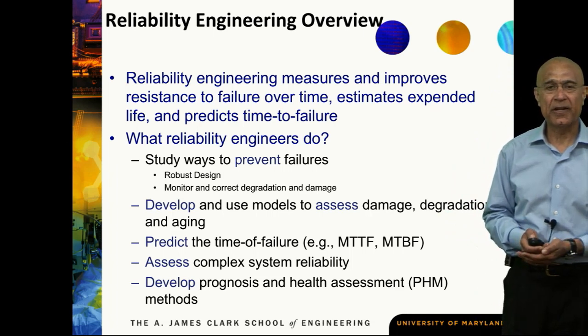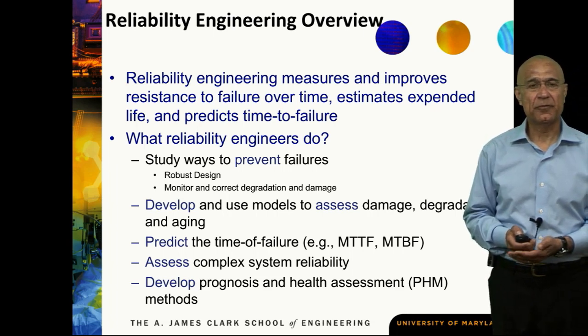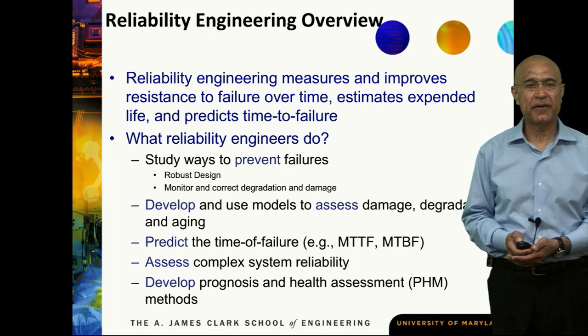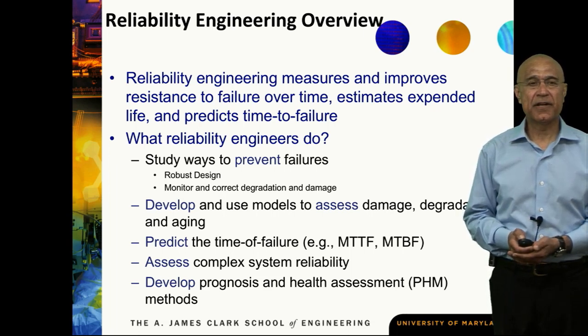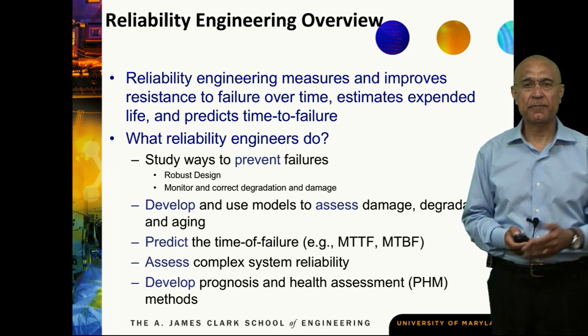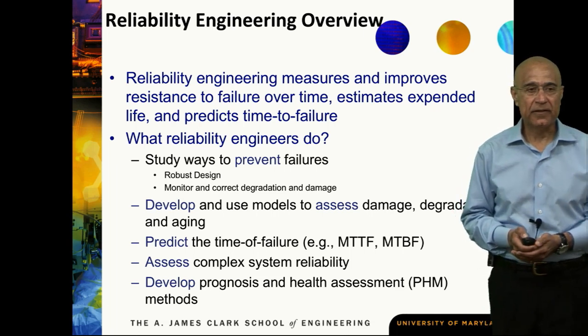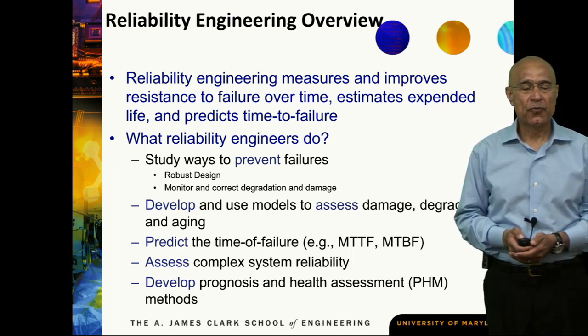Reliability engineers also develop and use models to assess the damage and degradation in equipment and the aging of equipment. They predict the time to failure, mean time to failure, and mean time between failures. These are the metrics for measuring and predicting how much of a mean life is left of the equipment, or the mean life that equipment can provide if it is new.